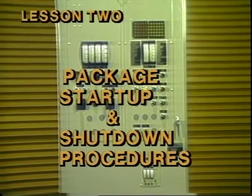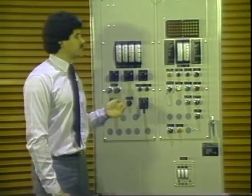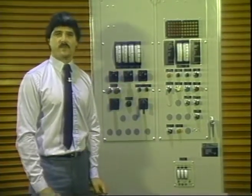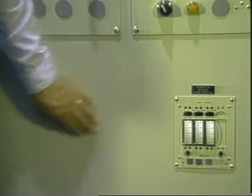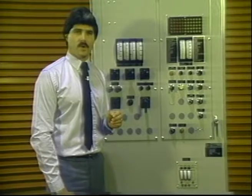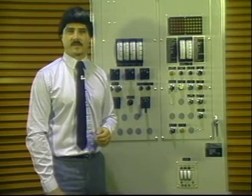Before proceeding with a package startup, you will need to become familiar with the location and function of the controls and indicators. You will find controls and indicators on several panels. The door of this freestanding control console contains an engine control panel and a generator metering panel. Some customer specifications call for a vibration monitoring panel and a generator winding temperature monitor panel. These options are installed beneath the engine and generator panels, as you see here. This particular package is only equipped with a generator temperature monitor. We'll also examine components installed on the DC circuit breaker panel located inside this console door and on the gauge panel at the forward end of the package.